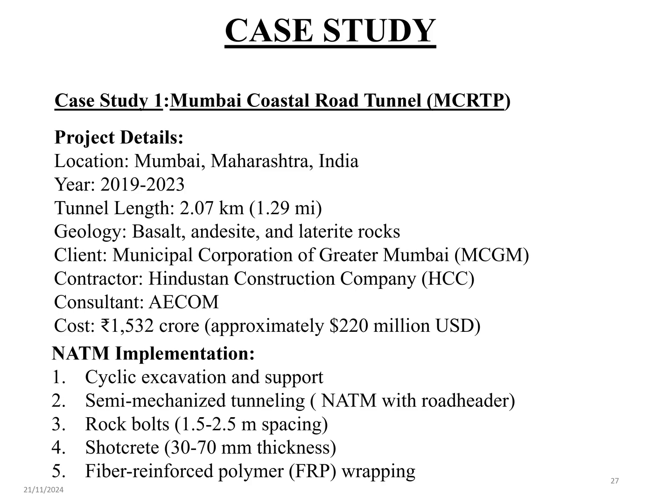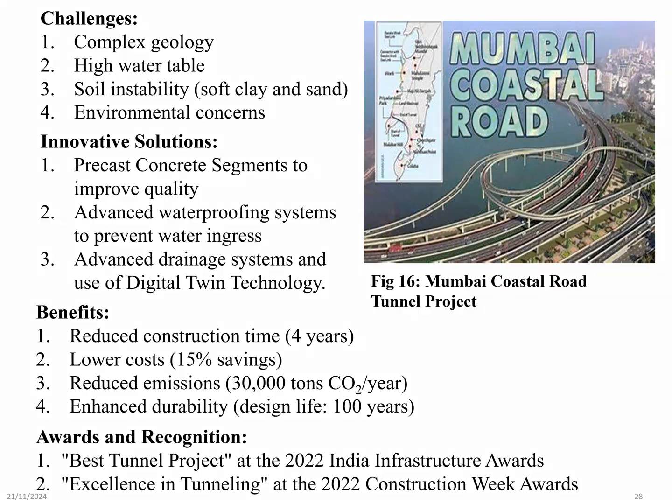NATM implementation: cyclic excavation and support to ensure stability. Semi-mechanized tunneling with a road header for efficient excavation. Rock bolts to reinforce the tunnel structure. Shotcrete for immediate support, and fiber reinforced polymer for tunnel structural integrity.